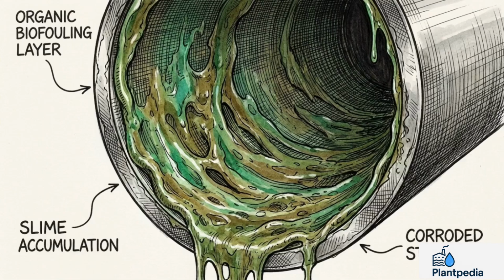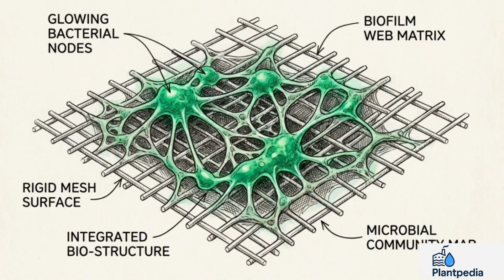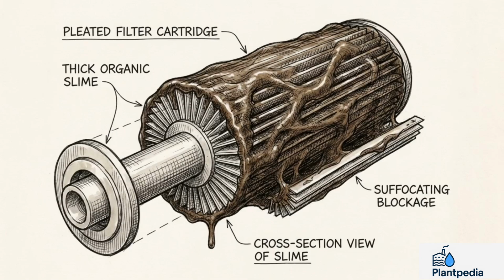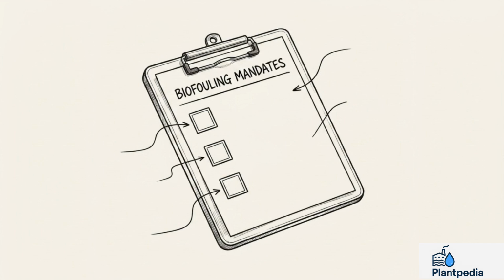Cause number 2 is biofouling. Rather than a mineral deposit, this is an active biological invasion triggered by specific environmental oversights. When inadequate pretreatment meets feed water temperatures exceeding 35 degrees Celsius, your system becomes an incubation environment for rapid biofilm growth. Eliminating biofouling requires 3 operational mandates.